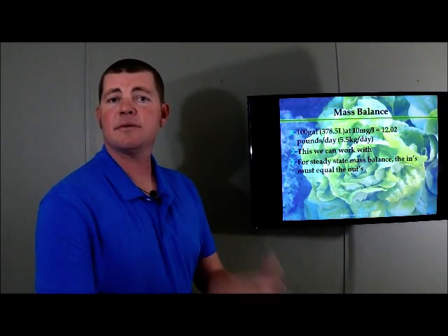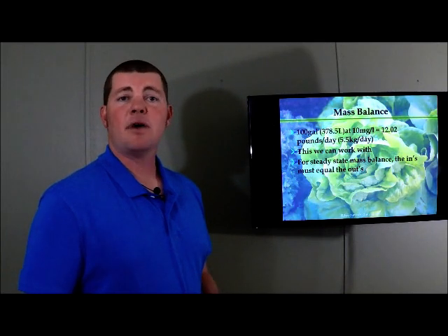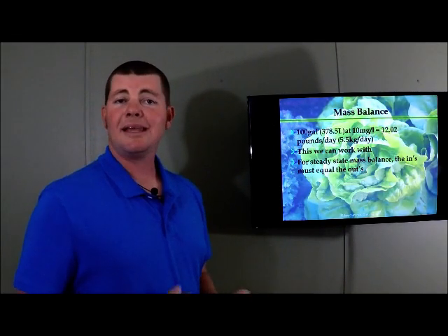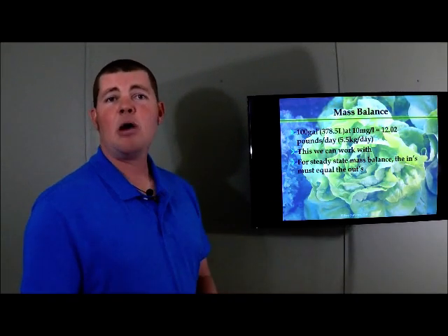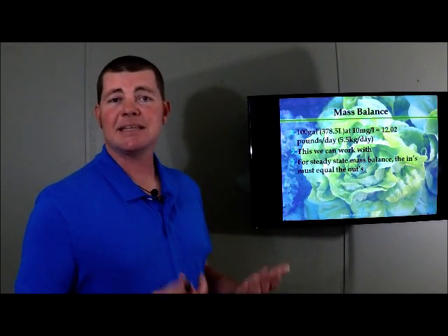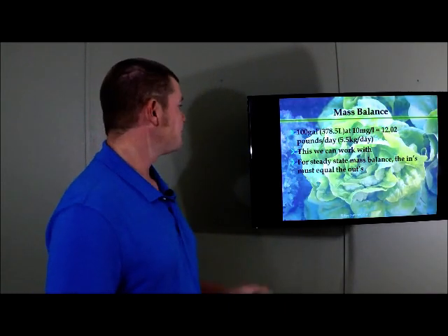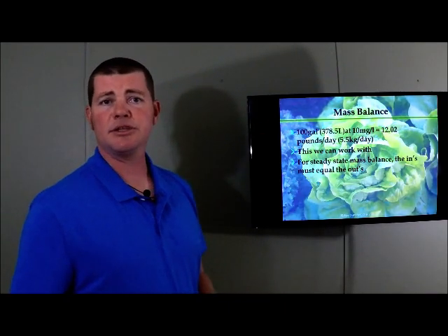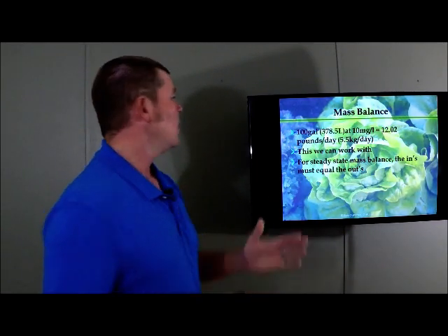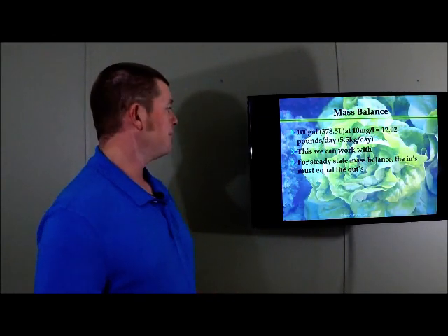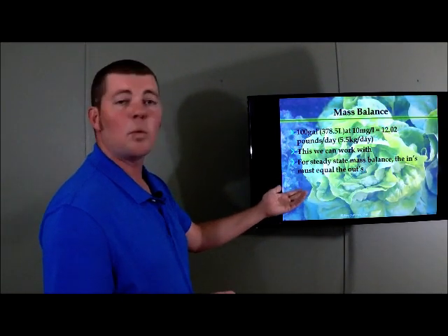Okay, we know how many pounds of oxygen we have going into the system every day. We can calculate how many pounds of oxygen the fish are going to consume by eating that food. So that tells us how much the fish need. Then it will tell us how much oxygen is leaving the tank. This is exactly what we need to design the oxygenation or aeration system. So again, don't get confused with that equation. We extrapolated it out as far as possible so that we could cancel and come up with a working number. For steady state mass balance, the ins must equal the outs.